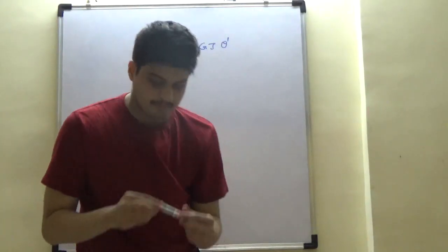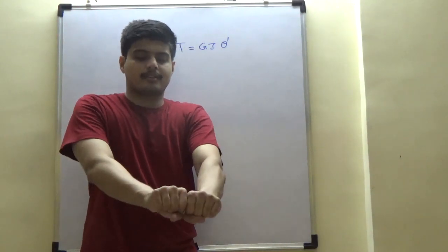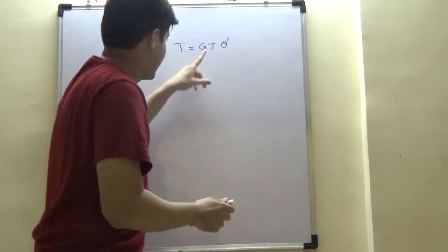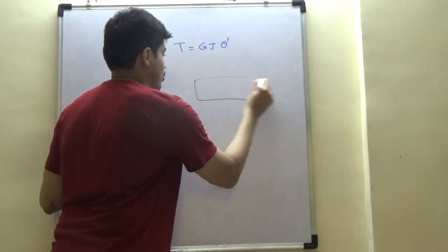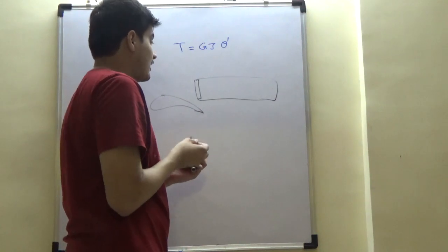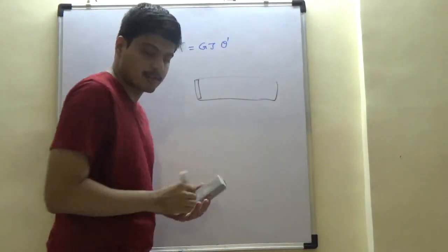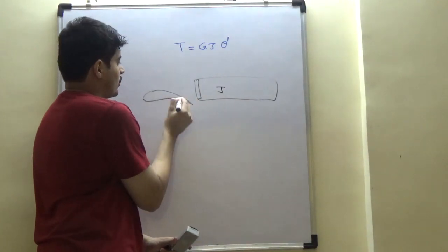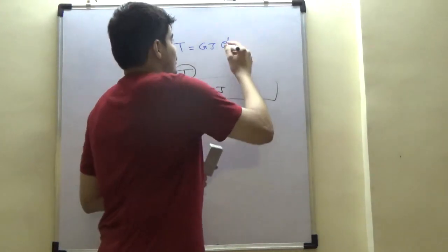Look at this marker. Small cross-section area, solid, bearing this. See, you cannot see any visible warping here, right? Cannot see. J is high. Right? So J plays an extremely important role because your wing structure, which is going to have this cross-section and aerofoil structure like this, is completely governed and dictated by the choice of the material, which determines G, of course, and then the structural property itself determines J. So this would determine my J. And in turn, for a given torque, I could see what the twist is.